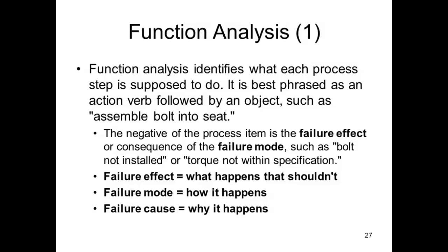The failure mode is how it happens. In this case, the failure mode appears to be the worker sometimes forgets to check the torque. The failure cause is why it happens, and we're going to see that saying the worker is inattentive or careless is not an acceptable failure cause in terms of actually solving the problem. The failure cause, again, was known previously as the failure mechanism.